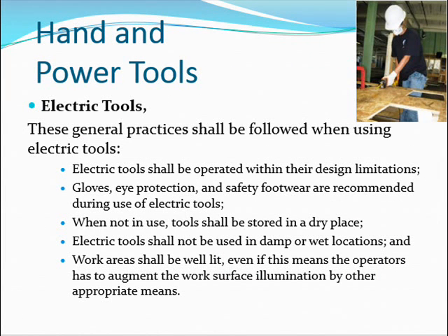These general practices shall be followed when using electric tools. Electric tools shall be operated within their design limitations. Gloves, eye protection, and safety footwear are recommended during use of electric tools. When not in use, tools shall be stored in a dry place. Electric tools shall not be used in a damp or wet location, and work areas shall be well lit, even if this means the operator has to augment the work surface illumination by other appropriate means.